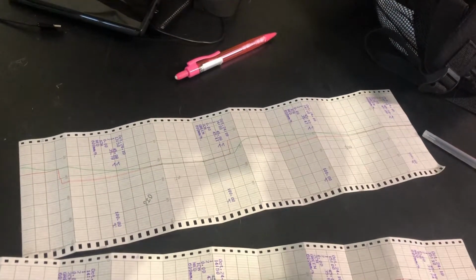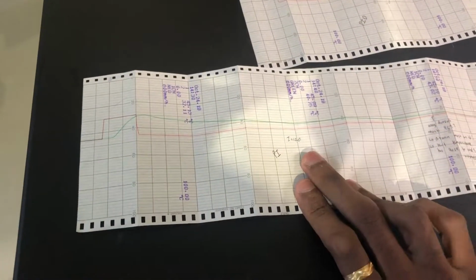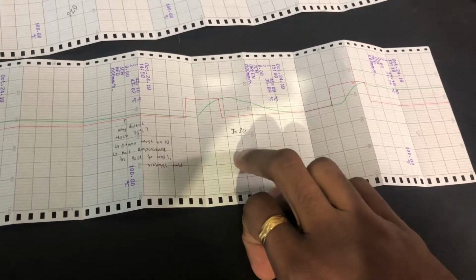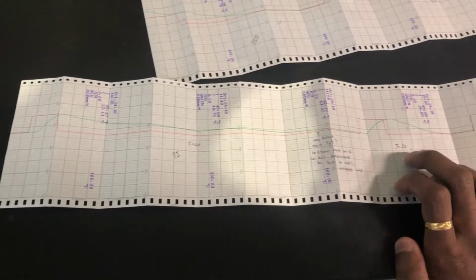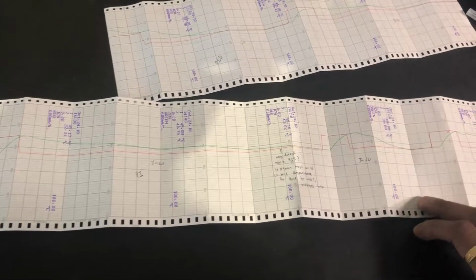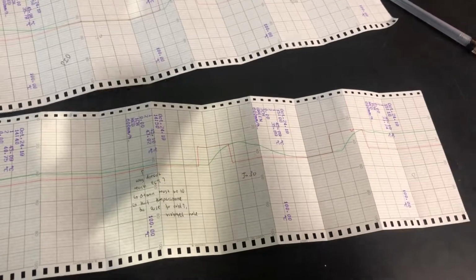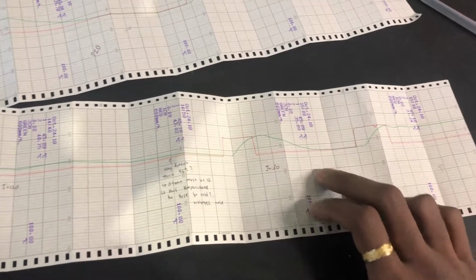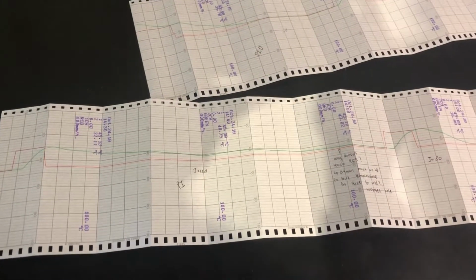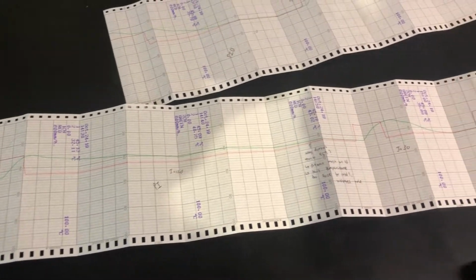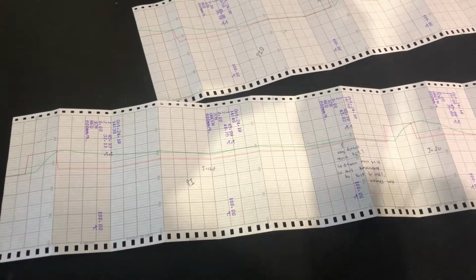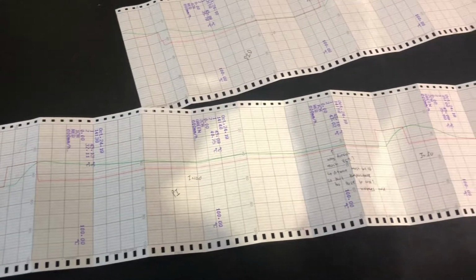Following to PI, over here, first the integral value is 120 and derivative value is 0, and here the integral value is 30 and derivative value is 0. From both of these graphs, we can see that when the I value is lower, it is easier and faster to reach the set point. This is because of the equation of 1 over tau I, which is proportional. So the lower the value, the faster we reach our set point.